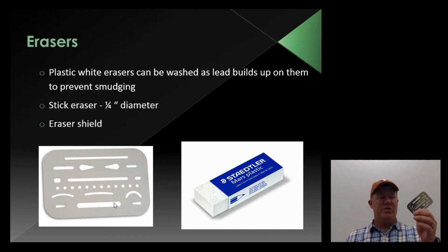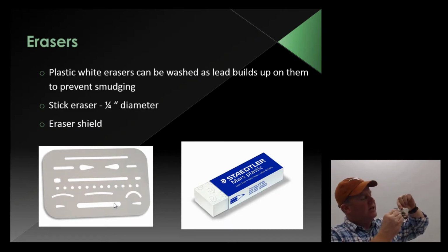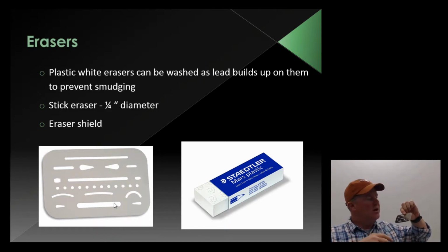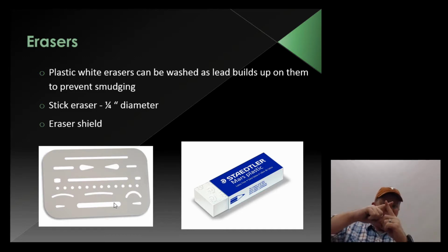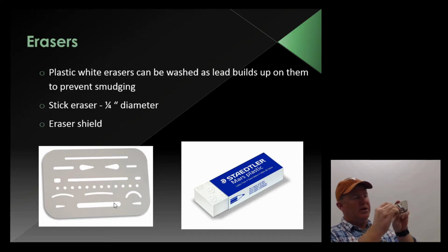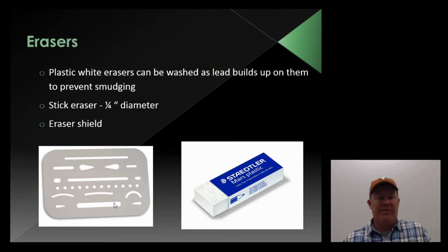And the erasing shield, guys, this will allow you to lay this on a drawing and actually erase inside of it. What it does is keeps you from erasing everything. So like if lines cross like that on a drawing and you need to get rid of the edges and square it up, take that erasing shield and lay over it and clean it up real nice.